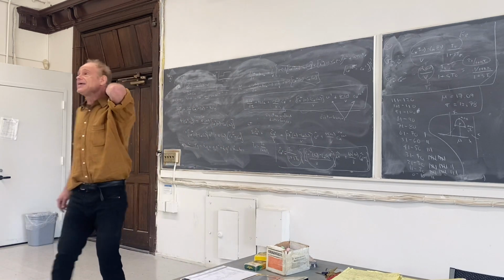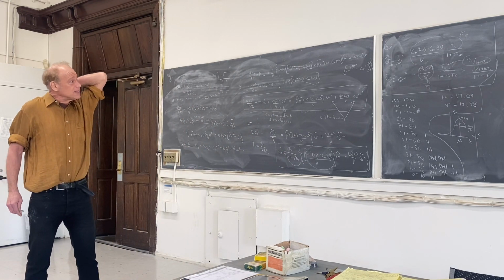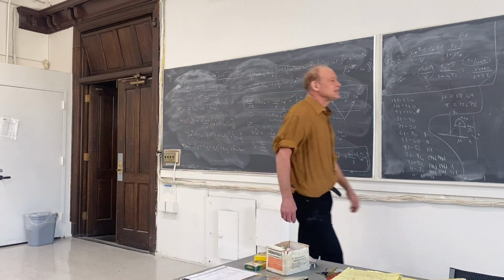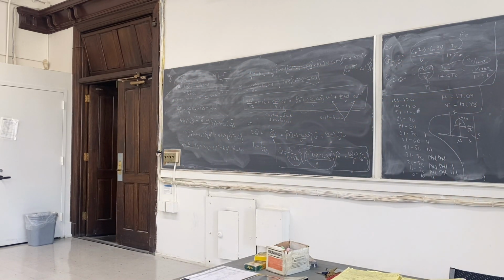And if you remember, at the end of the last hour, I just wanted to point out I made a slight error in the last second of the class. I had defined at the end of the hour what a transfer function was. And we said the transfer function was the Laplace transform of the output over the Laplace transform of the input. Now, if I have many outputs and many inputs, I have lots of transfer functions. So I have a transfer function for each combination of output and input. The main thing is it's where the input with the initial condition is 0. So that means I'm always dealing with prime variables where the initial condition is 0.